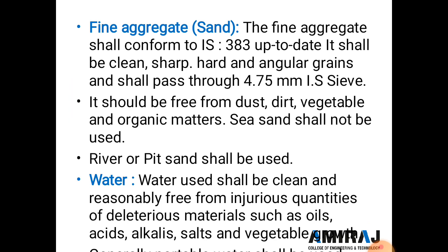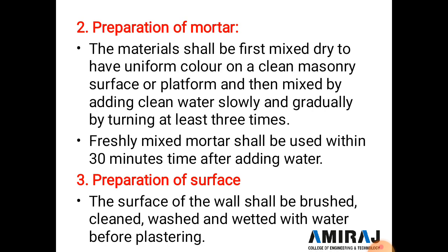The next material we use is water. Water should be clean and reasonably free from injurious quantities of oil, acid, alkali, salt and vegetable matter. The usable water should look like pure drinking water.